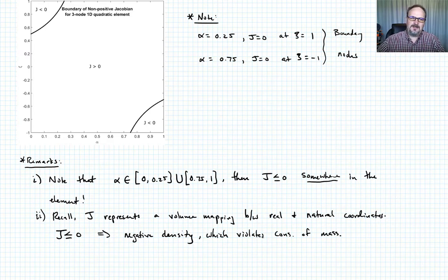And this is just a little insight into the problems you're going to run into when you try to build models with nonlinearity. You're going to find that your model crashes because maybe you're running Abaqus or something, and Abaqus says, no, I can't do this. Now you can begin to understand why that is. Abaqus says, no, you have an unphysical problem. Now this mapping doesn't work. I have to shut down. Okay?